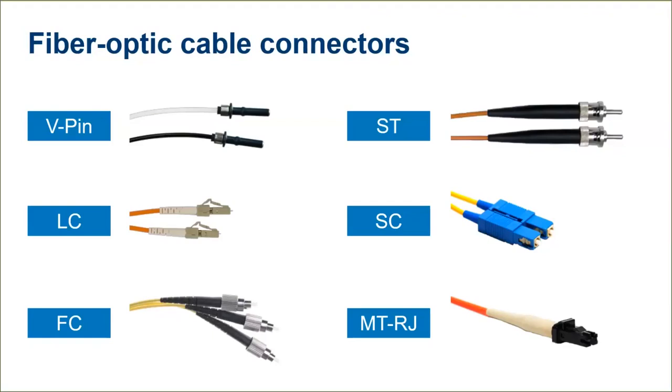Below that are the ferrule connectors, or FC. They are typically used in single-mode applications. These have a screw design, which was originally created for high vibration environments. Back at the top right, we have the straight tip, or ST connectors, also known as the bayonet fiber optic connectors, and they are primarily used for multi-mode applications, but sometimes seen in single-mode applications as well. The bayonet style of the connector provides a quick installation of a latching connector and retention.